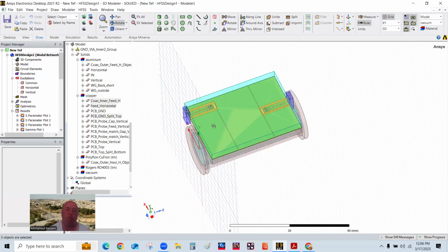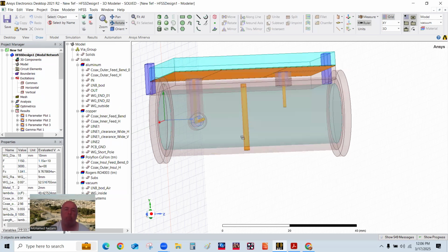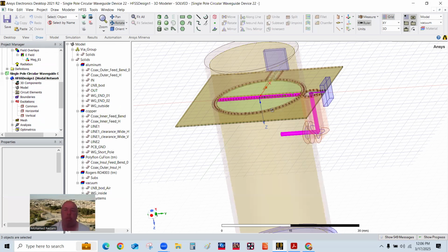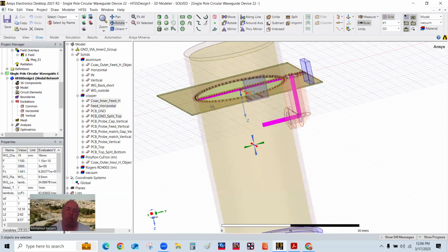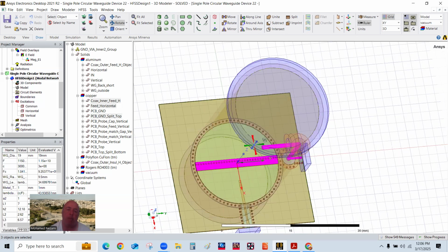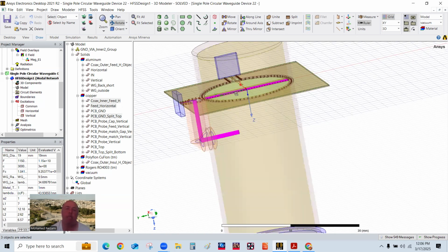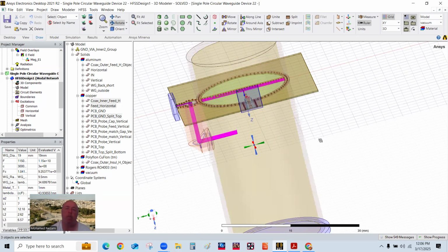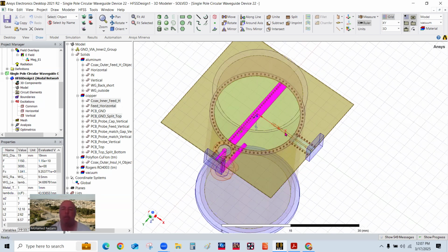Let's go back to the other one. This short pole in here is now implemented using a printed line, and that is shown right here. What I had is the board itself has, printed on the back and on top, a strip of line that acts as a back short for this polarization in here. While the other probe that is here, that's that guy right there.